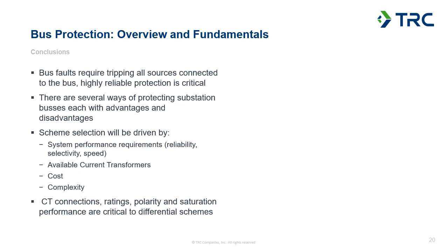And really, when you're applying bus protection, you have to have a good understanding of your CT connections, the ratings, saturation performance, making sure you're connecting up the relays and the CTs with polarity in mind. And that's really all going to be very critical to application of bus protection, specifically with differential type schemes. So it's certainly something you'll see a lot of as a protection engineer, and it's something to gain some familiarity with.